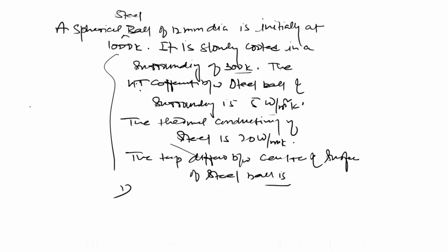So what is the criteria for the system to be lumped? The Biot number should be less than or equal to 0.1. And the Biot number is what? H into Lc upon K, K of the solid, H of the fluid. Very good. H is how much?